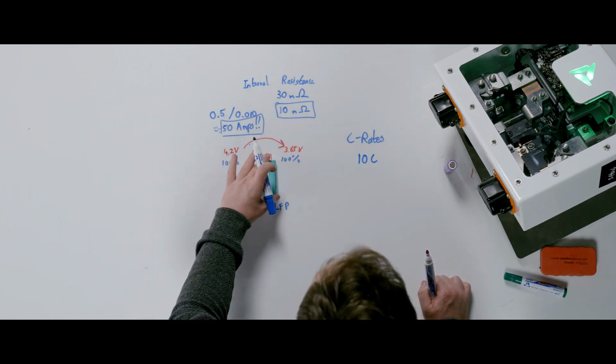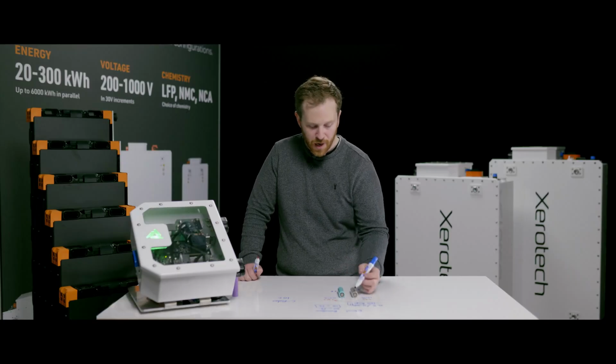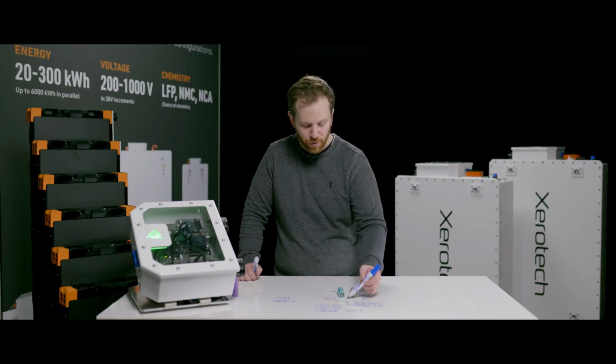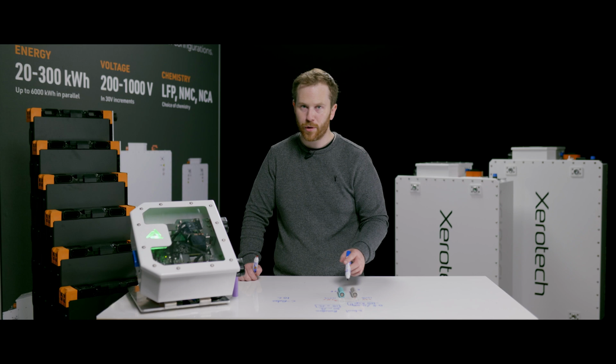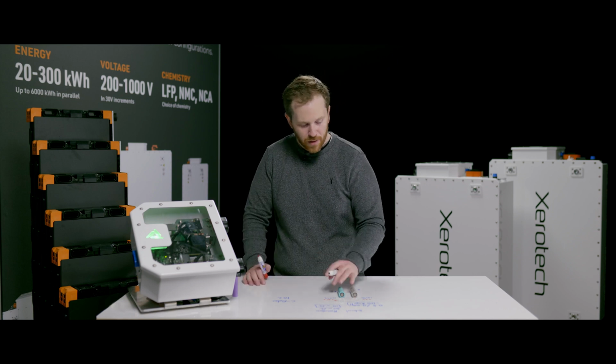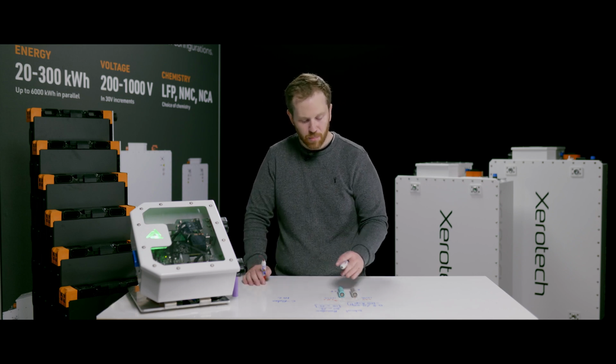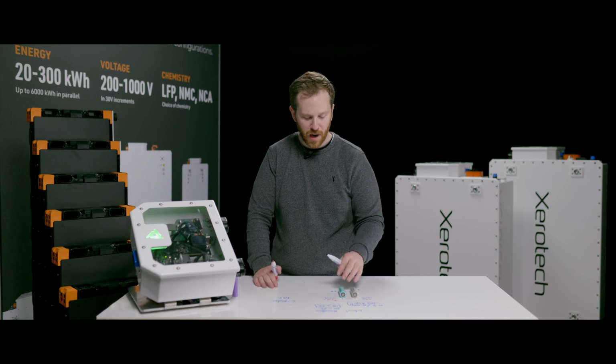There are some companies today offering this, but what they do is they've got a special piece of power electronics that deals with the voltage difference and manages it. This is also the reason why you never want to put very different voltage batteries of the same type in parallel at different voltages, because you'll get a huge flow of current from one to another.